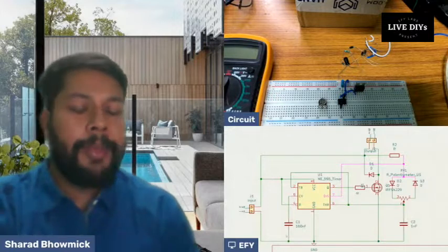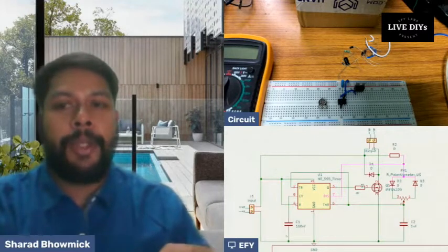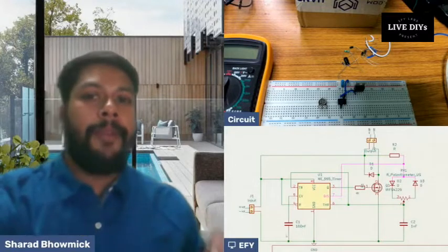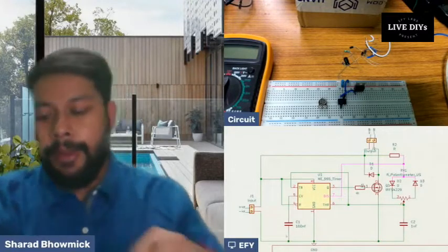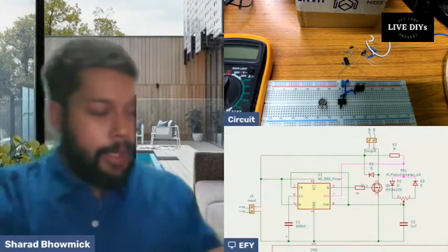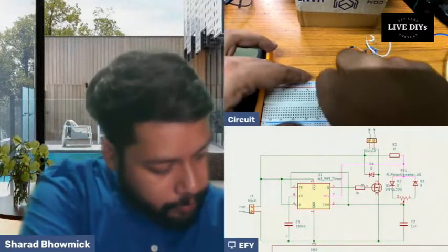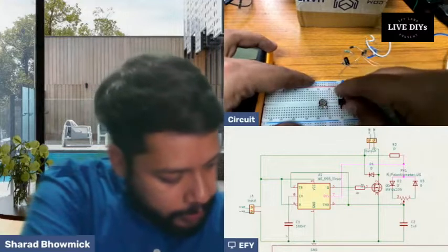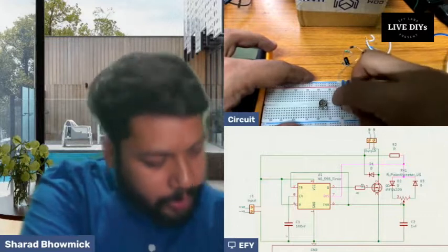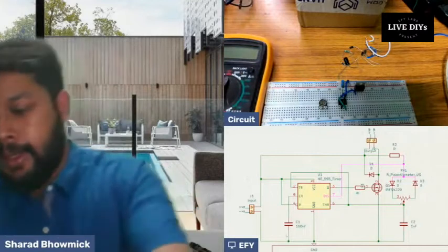without removing the battery, we can use a toggle switch, or we can use a switch in between fourth and VCC, or in between fourth and power output, and by just clicking the switch we can disconnect the circuit. So now I'll just connect pin number 4 with pin number 8. Pin number 4 is connected with pin number 8, and both the pins are connected to VCC.